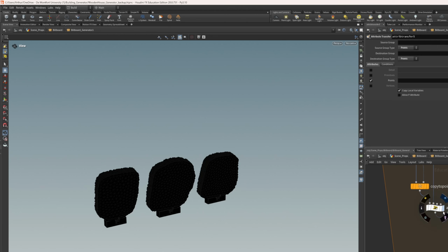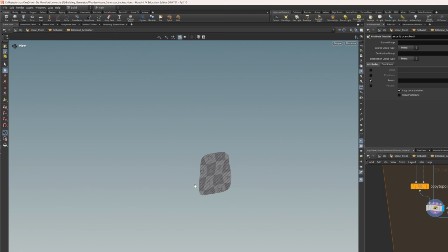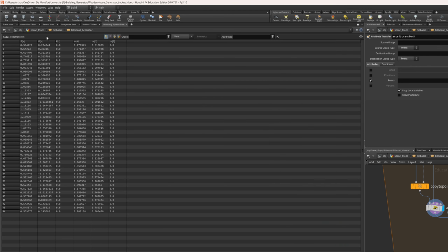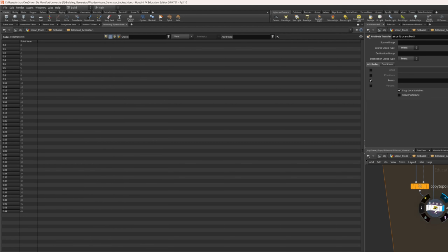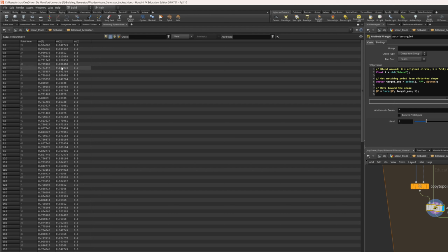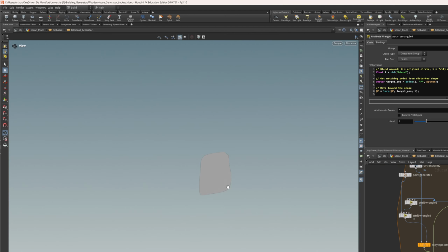The fix I ended up doing is that we took this shape, which had bad topology but the correct UVs, and you can't use an attribute transfer to transfer from vertex to vertex, and the UVs are saved in the vertex attributes, so they are here, and we need these on our other original shape, which is this nice clean one with no pre-cut triangles anyway.